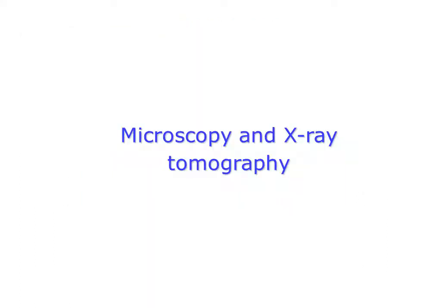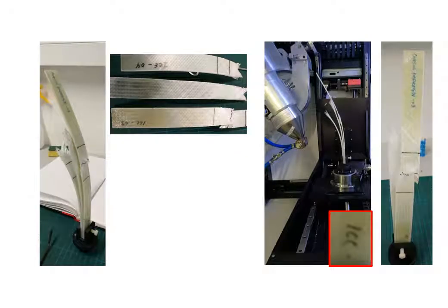In order to analyze the microscopic effects of different curing technologies, the samples were investigated by X-ray tomography. The samples were scanned with a polychromatic beam using a Nikon 225 and a Zeiss X-Radia Versa scanner. The reconstructions were performed using a standard filtered back projection, resulting in a voxel size of 9.64 micrometers.